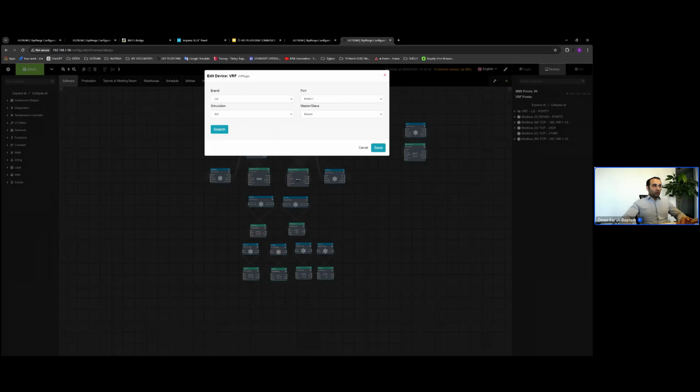The add-on will search, and if there are indoor units connected to the outdoor unit, and if they are all energized, they must be addressed as well. If there is no address for the indoor units, you cannot find them. They must be energized, they must be addressed.